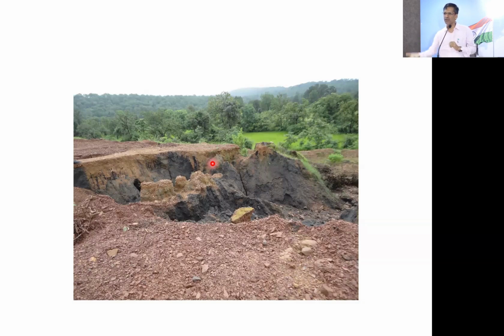Because otherwise there is no plantation. Anything below 2 meters, 3 meters, what nutrients are there? No nutrients, how will it grow? So for nutrients you need natural soil, and only then is it possible. So we tried to make a toe wall and drain around, and then we rehabilitated it, and then we abandoned it. This is not a good idea. They are putting it on land where there is no dike, no embankment, only a small pit, and above that they were covering with 0.5 to 1 meter of topsoil. So this procedure is almost closed now.